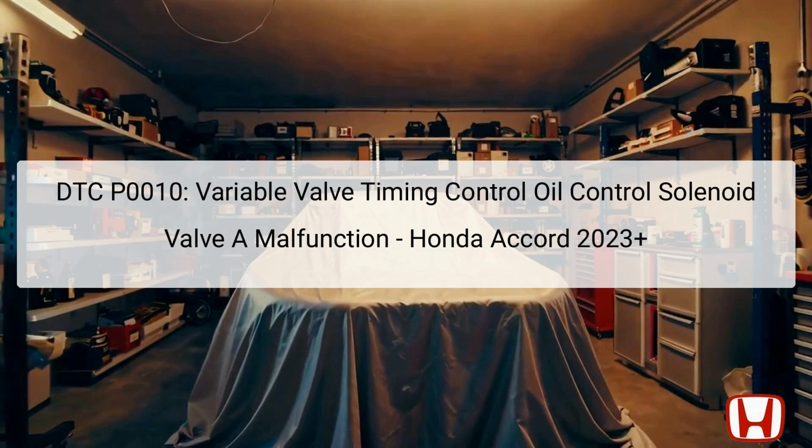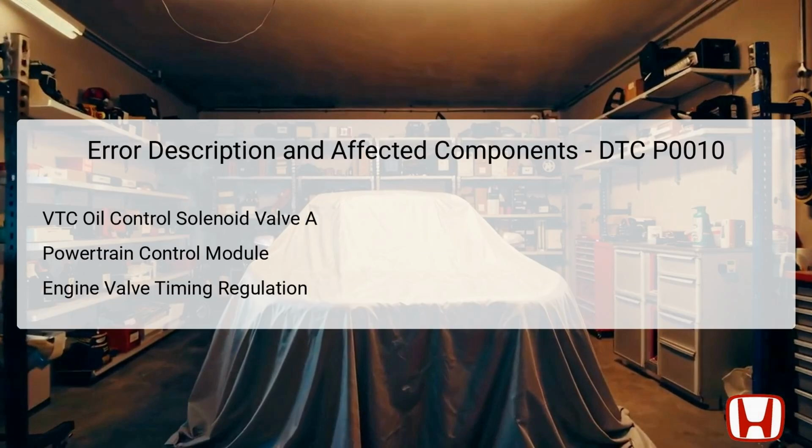of timely troubleshooting. The variable valve timing control, VTC oil control solenoid valve A, is vital for managing engine operations, as it influences the timing of the engine valves to optimize performance. Located generally near the engine's cylinder head, it regulates oil flow based on the engine's operational demand. The powertrain control module, PCM, acts as the engine's brain, gathering input signals and controlling output signals to various components,